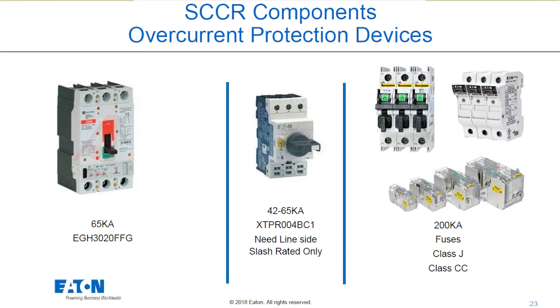Now, of course, if those fuses open, you're going to lose all of your motors. So you do want to make sure you're in a system where that's okay. Some systems, that's fine. You get one short circuit, you want the whole thing to shut down. But sometimes that's really not what you want. So that's the one cautionary piece of advice when I use a group motor instead. If you have a specific design like that, I've helped a lot of people, it comes up a lot. Please feel free to reach out directly to me and we'll figure out which one is best for your system. But usually the answer is to put a fully rated device in front of it, whether it's fuses or just completely replacing it with a fully rated component.